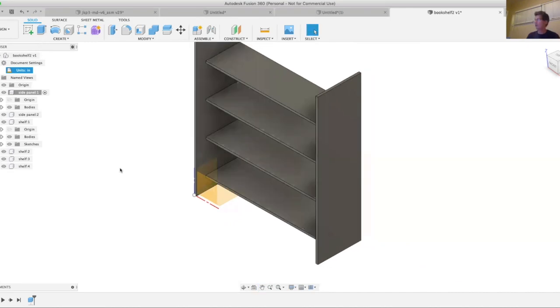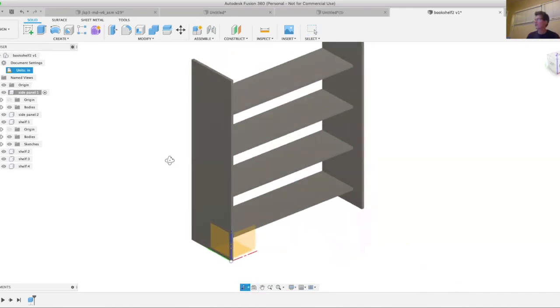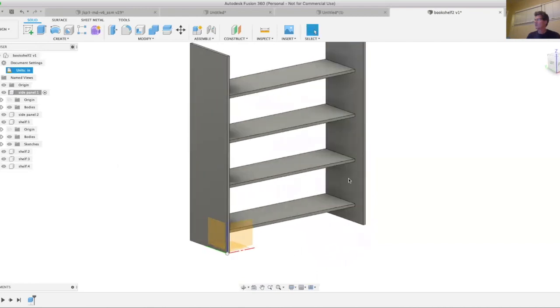Oh, come on. I'm pushing the wrong buttons. Okay. The pattern piece changed to 16 inches, but my shelves didn't. Why not? You didn't put a constraint in? Correct. So this edge snapped to the edge, but this edge didn't.